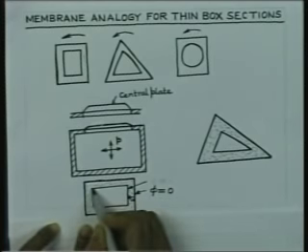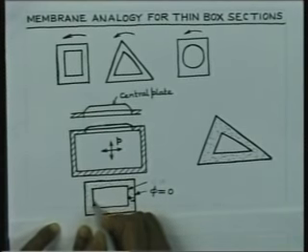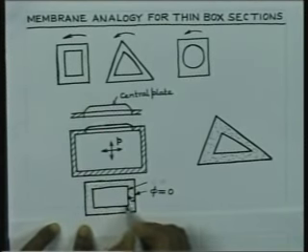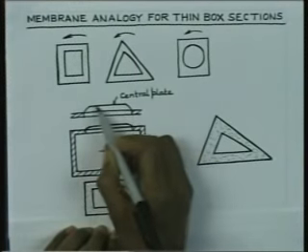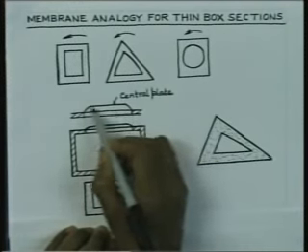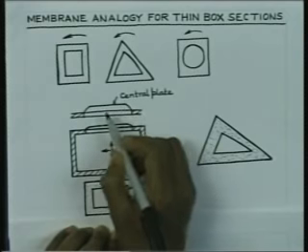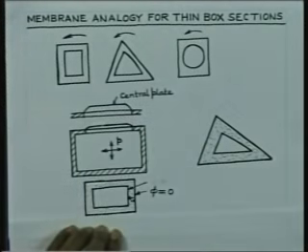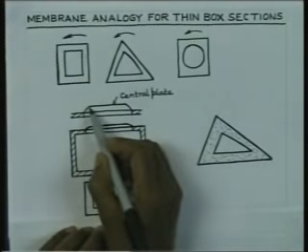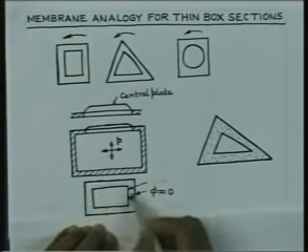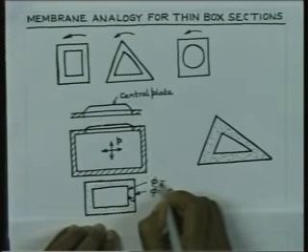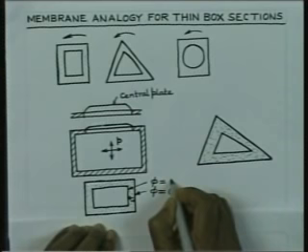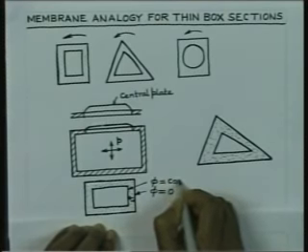So, therefore, all along this boundary, internal boundary also, the membrane deflection has got to be constant. So, while this membrane is deflecting, we must ensure that the deflection of the central plate is constant. So, there is a constant elevation of this central portion, and hence all along the boundary of the membrane we have the deflection constant, hence Prandtl's stress function is also constant.